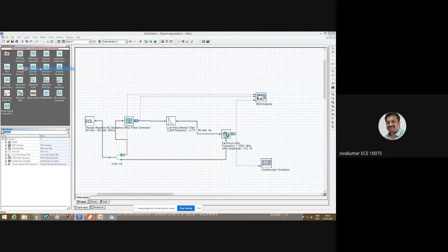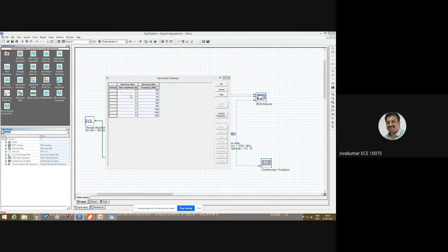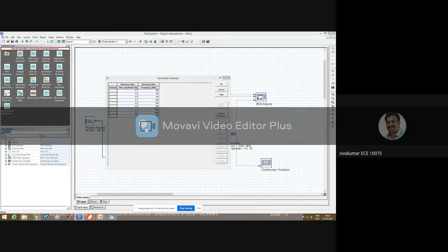Okay, just click in this manner, because I will post the OSD file in the chat box with these setups. Just analyze what simulated parameters and layout parameters are given, and based on that, note them down. Okay, here click layout, go to parameter sweeps.